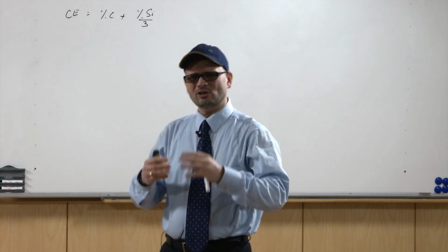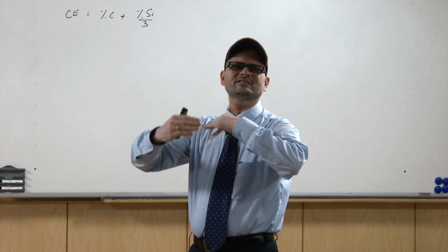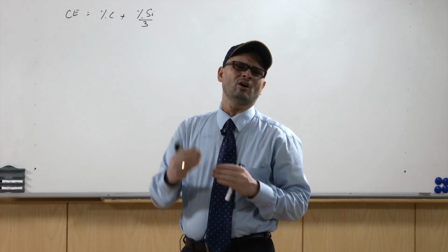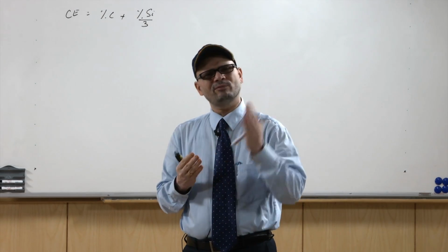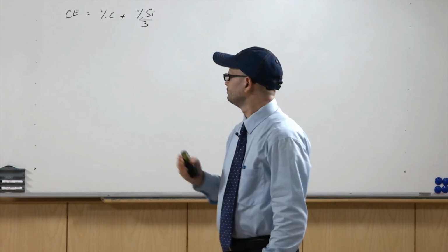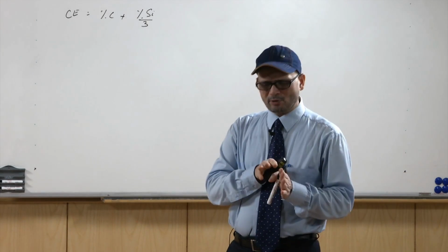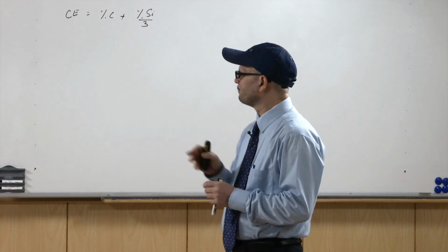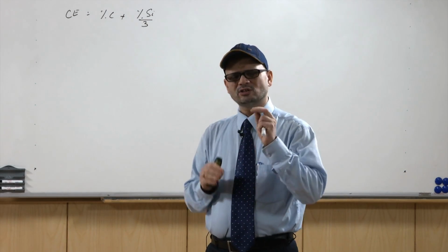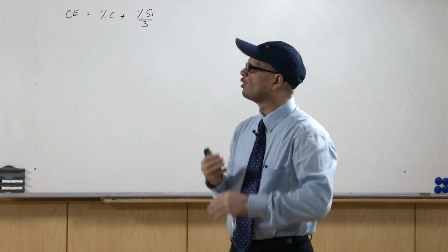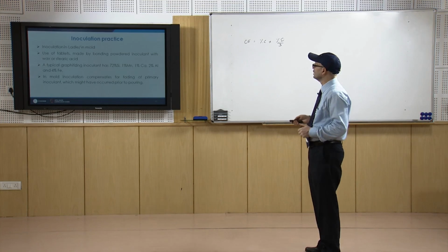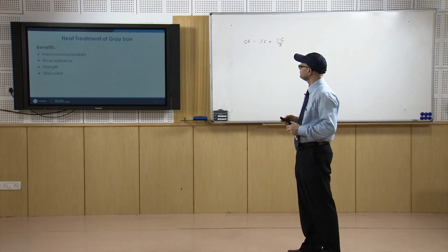You also do the inoculation in the mold, so that if there is any fading of the pouring inoculation, then during the process of going into the mold it can be compensated. So, for that we also do the mold inoculation.